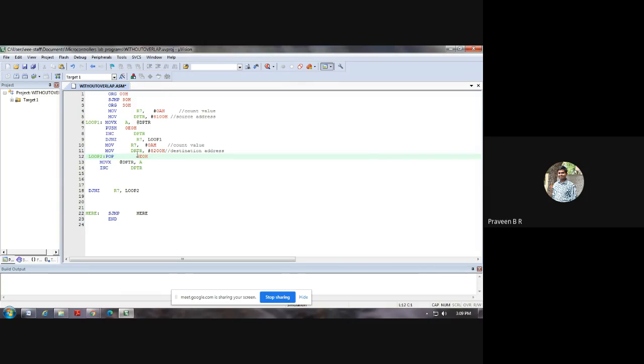The last data which you have fed to the stack will be the 8109 data. The data present in the 8109 memory location will be some number. That number will be popped out from the stack for the first time. After it is popped out to the accumulator, the data that is present in the accumulator will be moved to the memory location 8200. So 8200 will have the last data that you have fed to the stack. So that is how it happens.